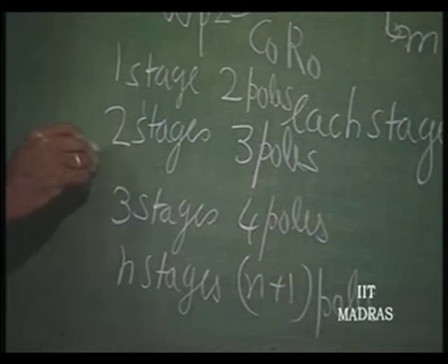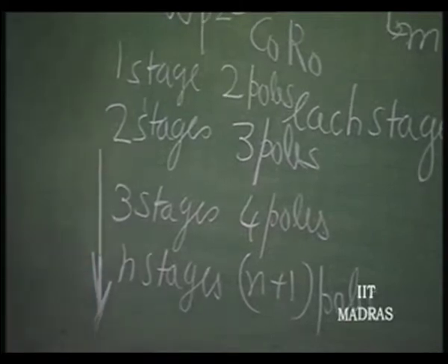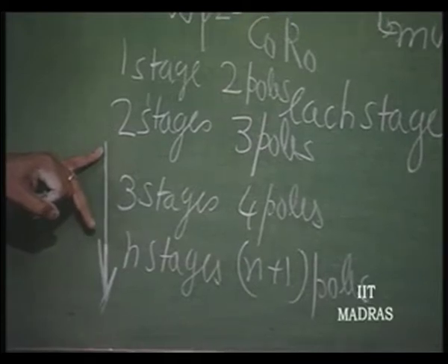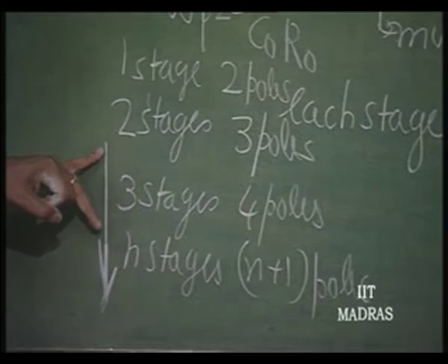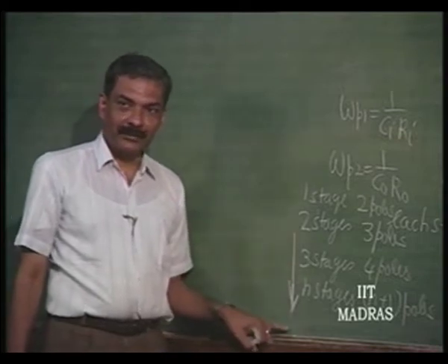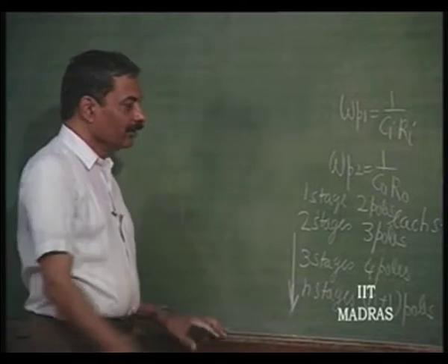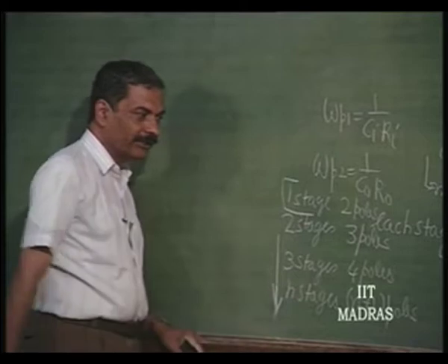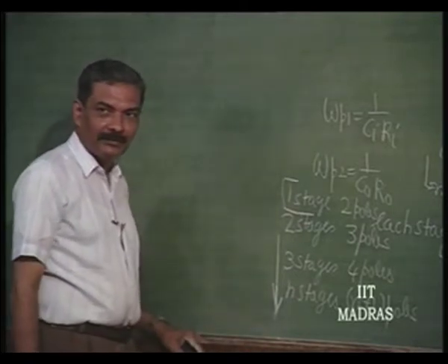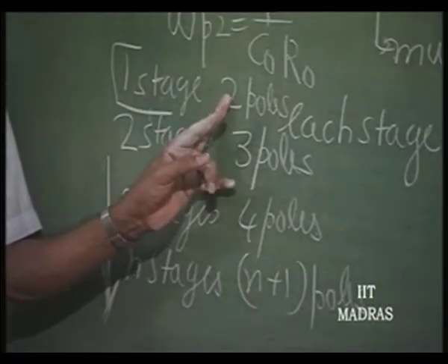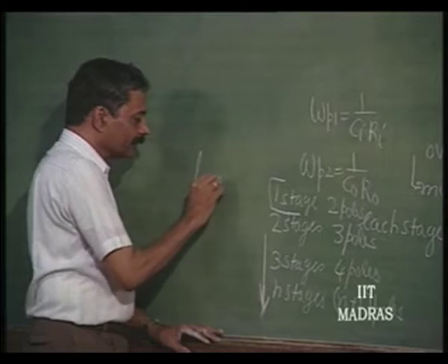So, normally overall feedback is not given because of the possibility of instability that will arise at frequencies above 2 stages, very rare. So, you will use most of the time for wideband amplifiers only one stage, which is pretty safe. A single stage is pretty safe for negative feedback. So, only local feedback is preferred.